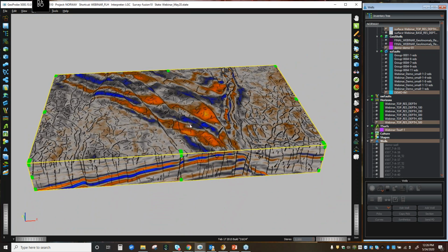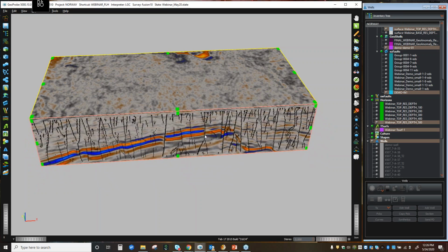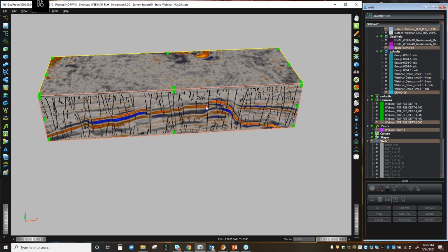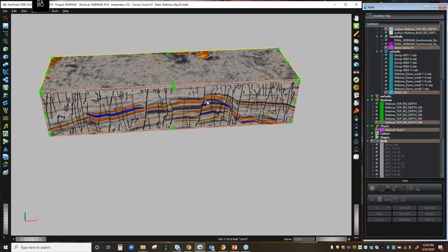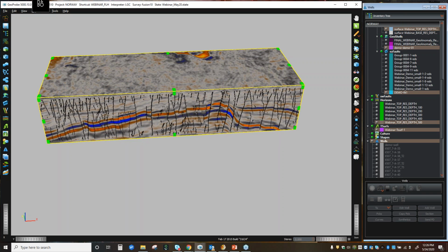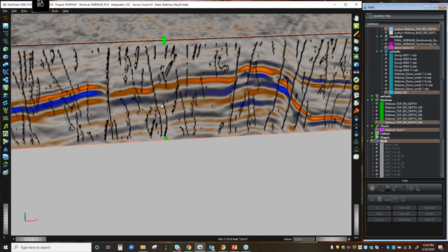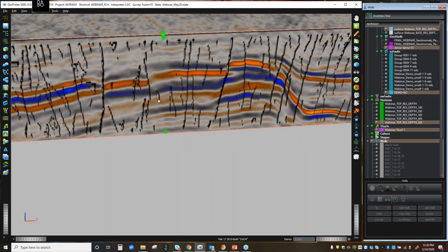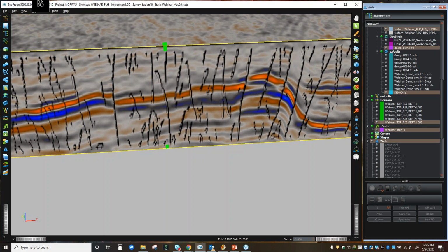Also on the vertical section display, this is my reservoir, as I mentioned. As you can see, the fault definition is quite nice, with displacement, and I can QC as well, that the faults are there where they're supposed to be. There's nothing which gives me an indication that there is no fault and yet the software has created a fault. So you can see in this area there is a fault. The software will create the fault as per the tip and the azimuth of the fault when it moves and when it turns and twists around within the seismic volume.